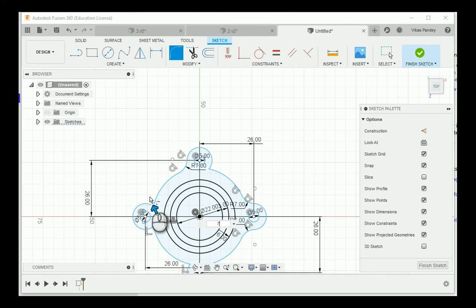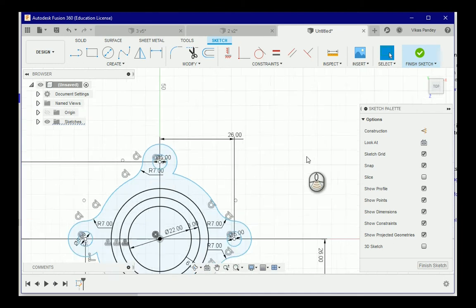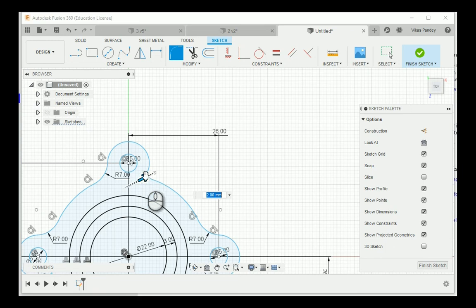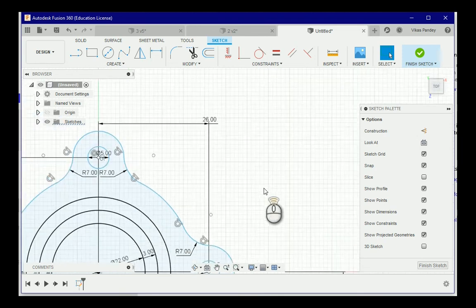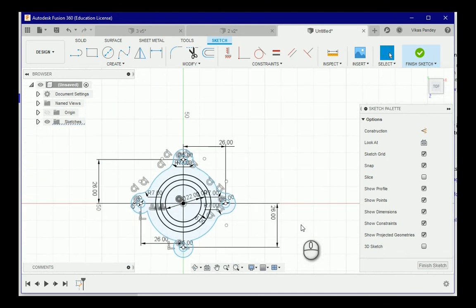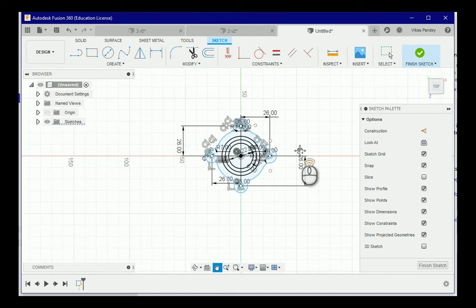So we'll begin by finishing the sketch first. Let's do it. It appears we are creating tangents, but in some cases you might not need to create tangent, and you might need to create some other object. It's better to have tangent because the surface will be smoother in that case, and the prints will also be better. So let's zoom it, actually, panning it a bit for coming into view.